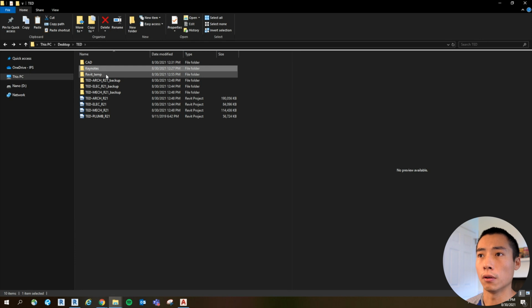And then over here, you'll see the Revit temporary files. You generally don't touch these. And then these are the actual Revit projects. So how this works is that each project will link in the other projects as an overlay. So you can see the background from the architect with the mechanical equipment and the plumbing piping running through there. But when somebody takes your project and links it into theirs, all those overlaid links won't follow through. That way you don't get a circular loop.